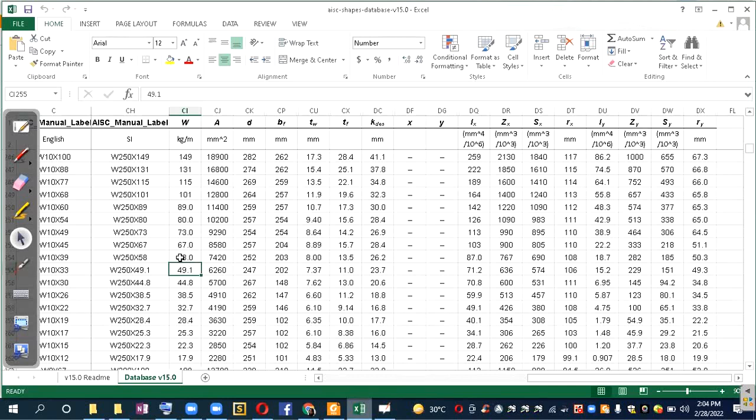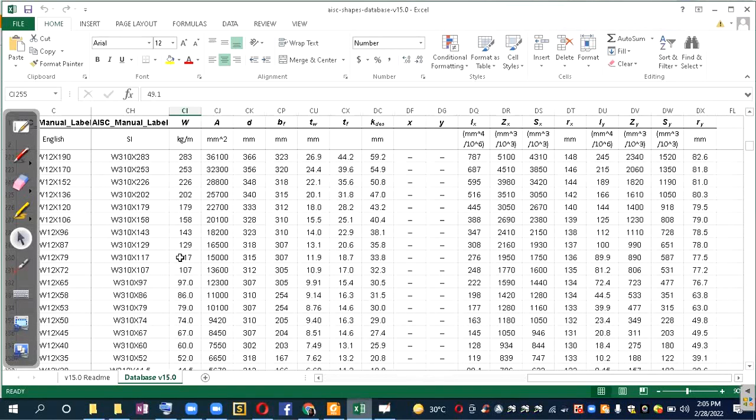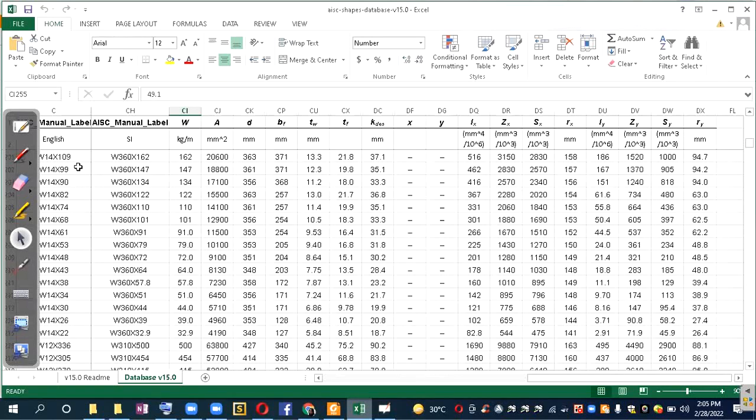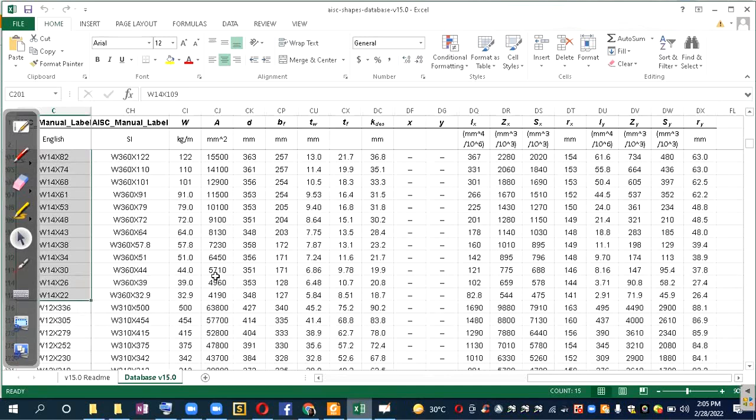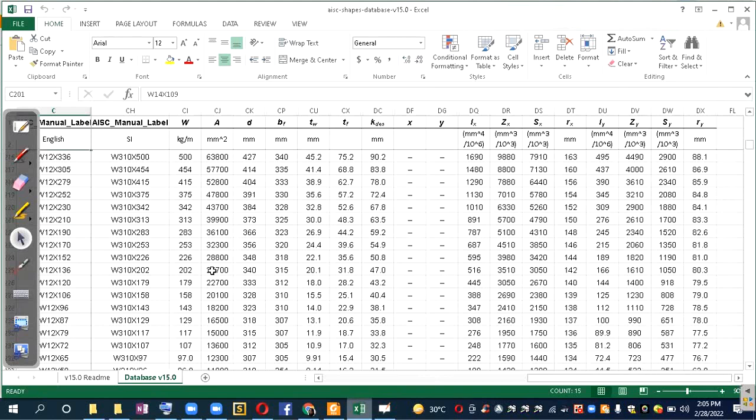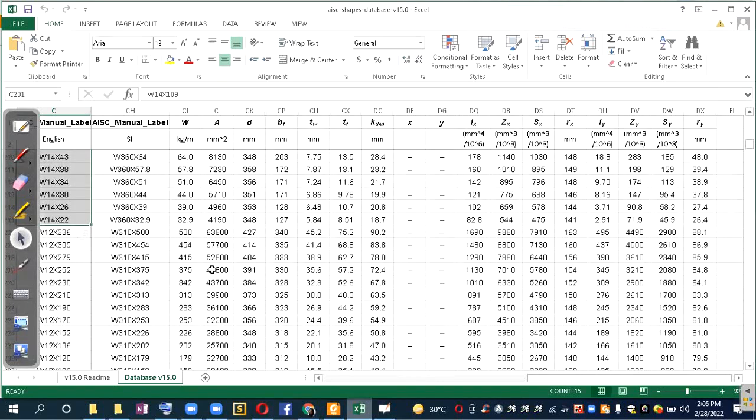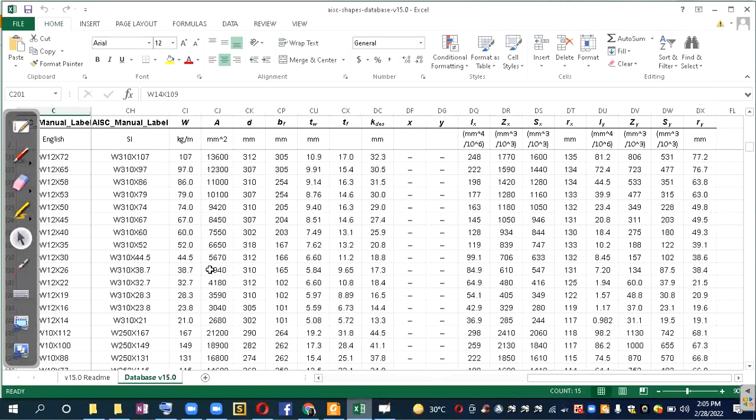Okay? Pagka in-indicate po na ang kukunin nyo is W14 o may depth na kayo, you have to focus in selecting yung trial section ninyo doon sa W14 lang. Okay? So, ganyan. Kaya nag-focus lang tayo doon sa W12. Naka-specified kasi sa problem na W12 yung gagamitin. Okay? Pagka wala, i-try nyo lahat ng W section na pwedeng economical. Lalo na pagka binanggit sa problem that you have to select the lightest or yung select the most economical section. Okay?